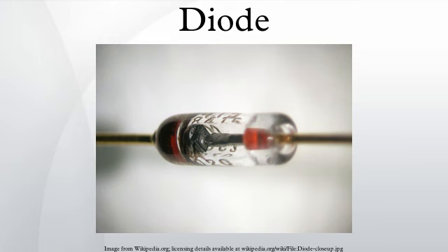Over voltage protection. Diodes are frequently used to conduct damaging high voltages away from sensitive electronic devices. They are usually reverse biased under normal circumstances. When the voltage rises above the normal range, the diodes become forward biased. For example, diodes are used in motor controller and relay circuits to de-energize coils rapidly without the damaging voltage spikes that would otherwise occur.